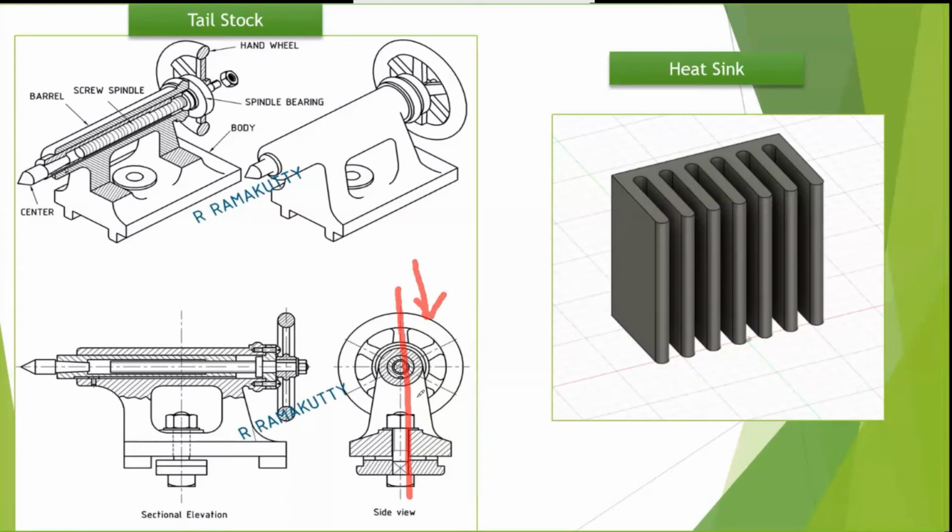So if you want to draw a tailstock in Fusion 360, you have to first draw its circle, then another, an internal circle, the rims, the inner diameter, the bush outer diameter, bush inner diameter, the pin inner diameter. So you have to draw it, and it's quite complicated even in drawing the sketch.